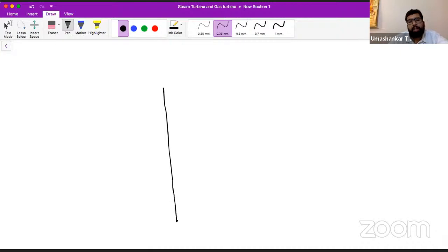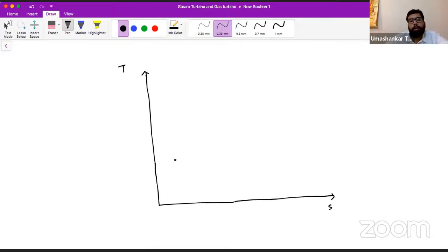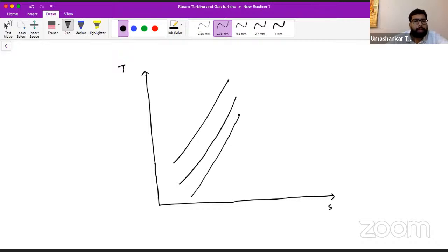If you have attended all the lectures, then yes, pressure is constant. As I said, the reheater is also a constant pressure device. So our game is again in three pressure lines. Let us first make three pressure lines. In this cycle, compression is happening in one stage only. So our air reaches from the inlet pressure to the maximum pressure in one stage only. So we are reaching this point 2 in one stage.